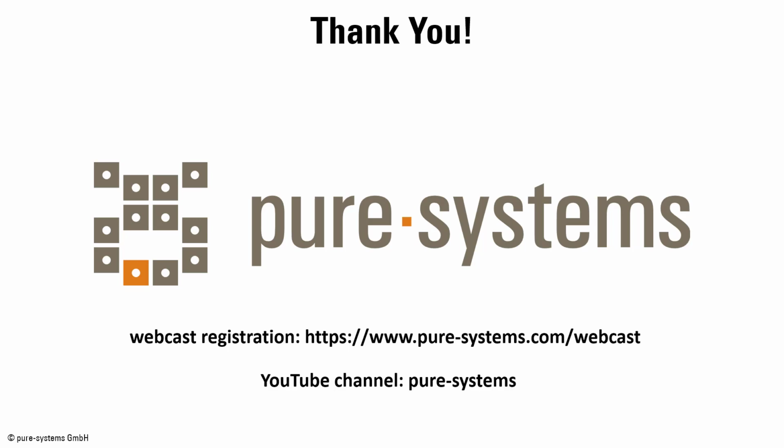Yeah, good question. And actually, the answer is yes. We only saw it briefly in today's demonstration. You can make use of constraint elements in Enterprise Architect and convert them to Pure Variants constraints. And there you can write your PV mapping rules into, and you can then use transitions to connect these constraints to multiple elements in your diagram. And then this constraint will affect all of those elements and even transitions. So you can also connect this directly to another transition to make this variable.